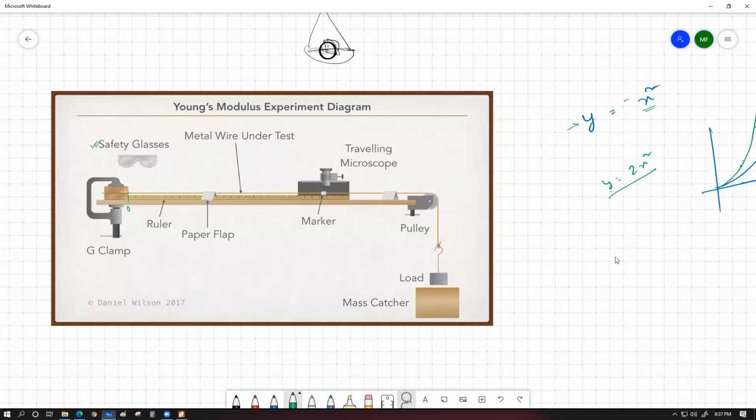because in that case we have to observe a curved surface. So we are not going to do that. What we are doing is placing a small piece of marker over here. This is actually a piece of paper marker that usually looks like this. So this is a bit of a corner. We glue this onto the wire, or we tape this onto the wire. The gluing force or the taping force adds very small resistance to the deformation. So we just do that over here.